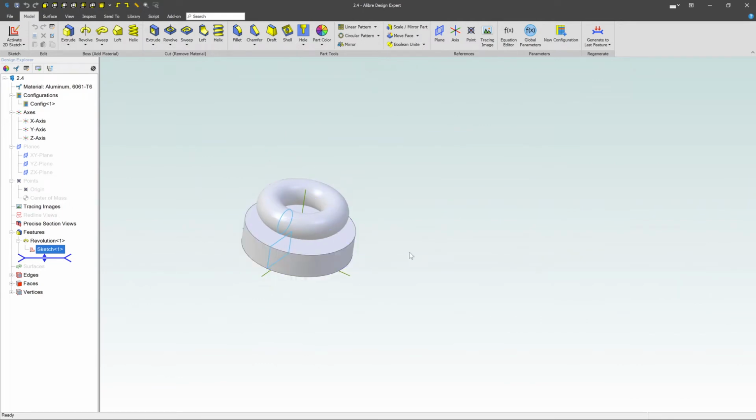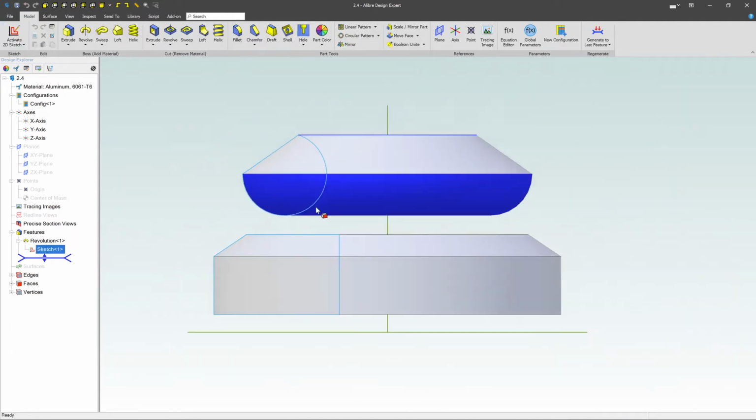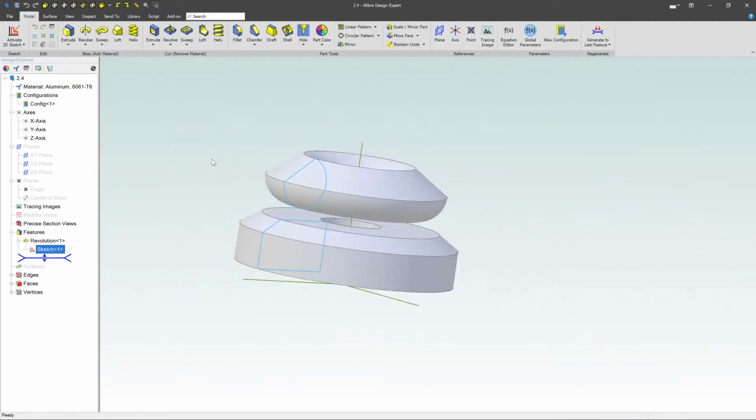So that makes sense. Now, if I wanted to make a cut, for instance, I could, of course, go back here to the sketch one more time and say, hey, let's trim off a corner. So I'm going to make a line here and cut that off. And do one more little cut up here, and then I'm going to do some trimming. I'm going to trim this away. I'd like to get rid of that. Get rid of that. Let's get rid of that. And let's trim these corners off here. So we're going to give a preview of using that trim tool. Right, so I'm trimming both those things away, deactivating the sketch, and of course that modifies both of those parts because I've trimmed away that upper corner of each of them.